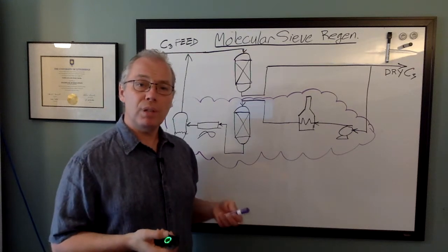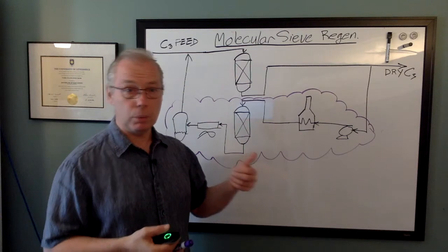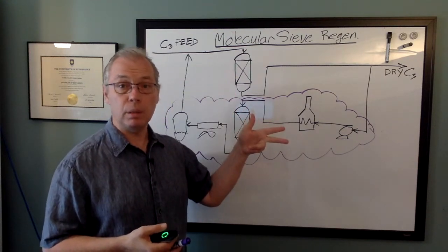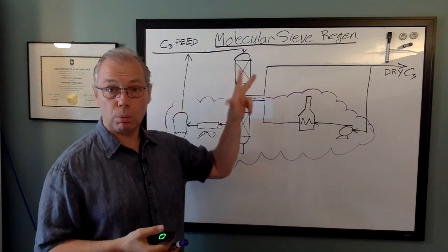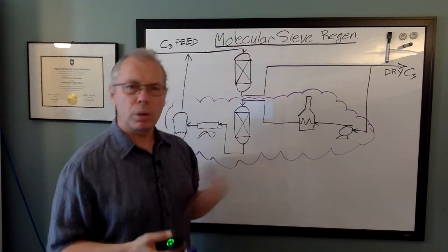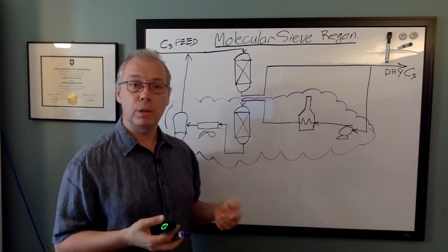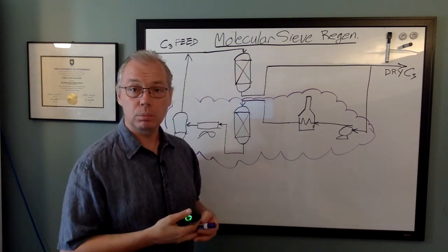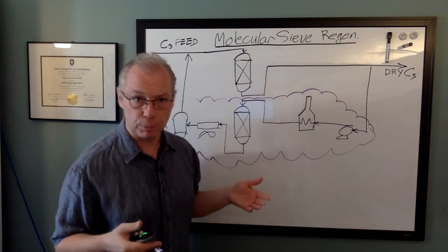Now, our CFD model must determine how density, or specific volume, volumetric flow, and fluid enthalpy evolve over time in our 1D geometry. And note, we've got three variables that we have to figure out. We need three equations. We also need to determine some way to figure out the amount of heat that is transferred to or from the fluid from our source of heat. And for this whole situation, we'll make the simple assumption of constant pressure.